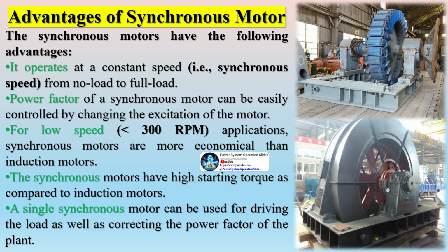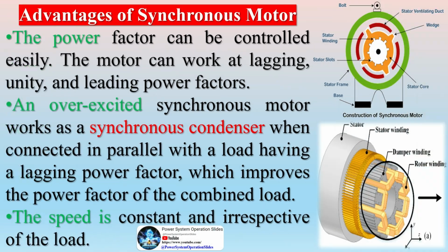Advantages or merits. One of the major advantages of using a synchronous motor is the ability to control the power factor. An overexcited synchronous motor can have a leading power factor and can be operated in parallel to induction motors and other lagging power factor loads, thereby improving the system power factor. Synchronous motors can be constructed with wider air gaps than induction motors, which makes these motors mechanically more stable. In a synchronous motor, the speed remains constant irrespective of the loads.